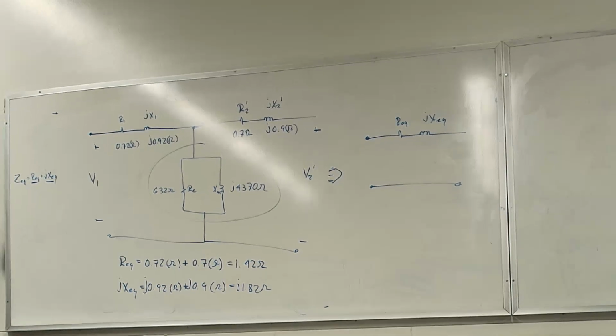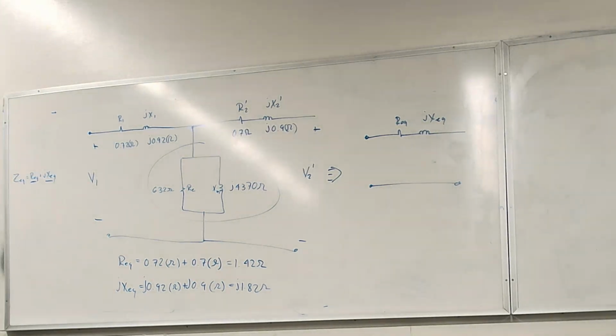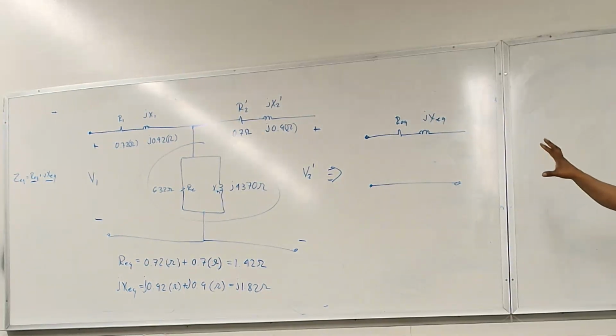We did a lab last week, right? For the machines. And we were trying to find the impedances of a synchronous machine. So you can determine these values, these resistances, these reactances, by test. All you need is a nice voltage source and a good, well-calibrated multimeter that can measure current, voltage, real, and reactive power. And then you can come up with this value. So we'll do that. The point I'm trying to make is that there are multiple ways for you to obtain this kind of information.